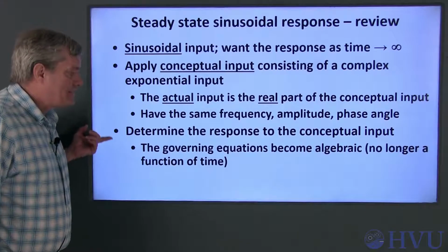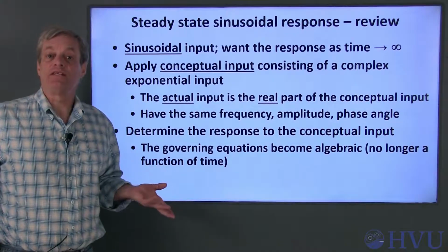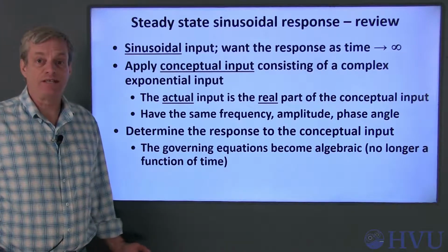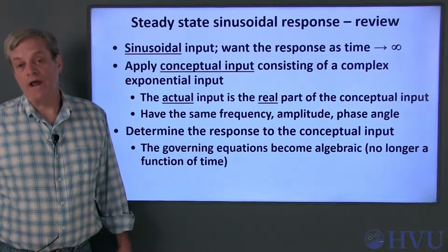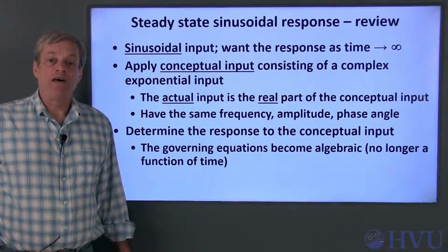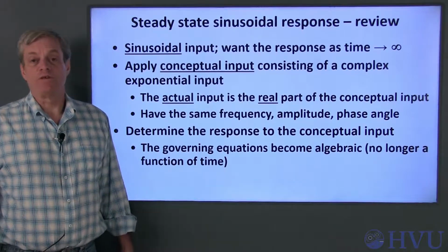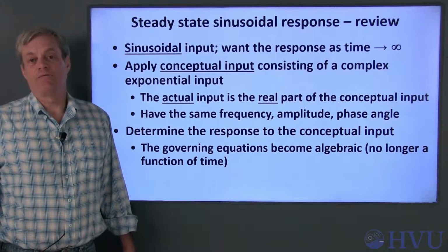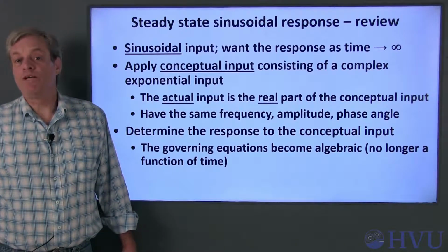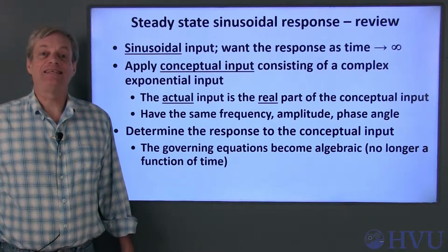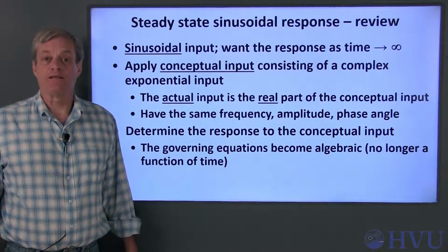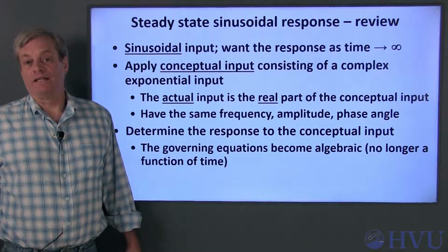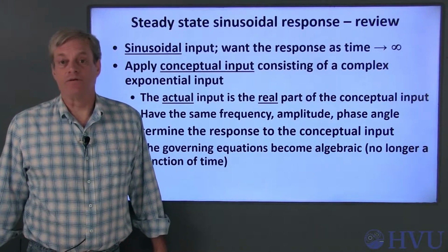In sinusoidal steady-state analysis, the system response will also be a complex exponential with the same frequency as the input function, but with an unknown amplitude and phase angle. These values are represented by phasors, as we saw in the previous video. When we substitute the complex exponentials into the governing differential equation, the differential equations become algebraic and any time terms cancel out of the response. This only happens with linear differential equations, which is one reason why linear systems are so popular with engineers.